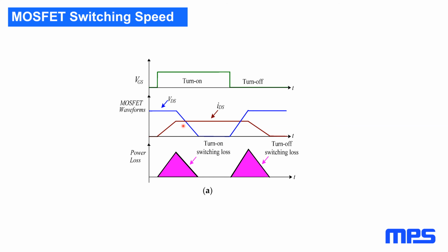Maybe you've got a current shunt resistor you have to think about before that current gets back to the gate driver IC. I don't know how you can measure it. You can sort of take a guess at it by looking at the PC board design. Maybe you can infer what it is based on measuring gate drive current and voltage, but that's pretty hard.